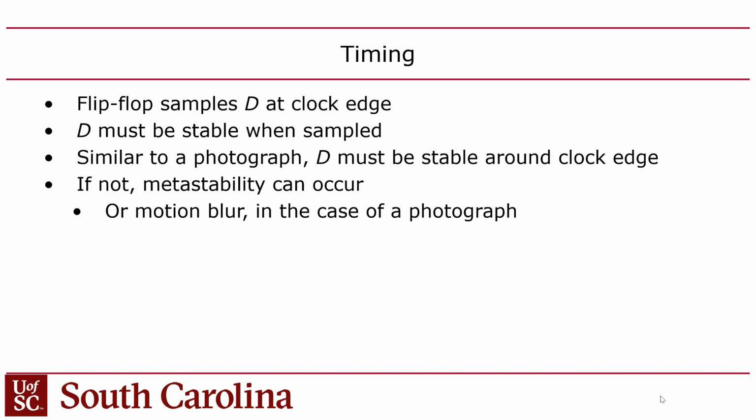If you add the setup time and the hold time, basically that creates an aperture around the clock edge. So you've got the clock edge, and then this time before and this time after the clock edge. And again, the clock edge is measured from the halfway point. So when the clock is transitioning from, say, low to high, and it's a 5 volt signal, when it hits that 2.5 volt halfway, there's a time before that, the setup, and a time after that, the hold. That time span is called the aperture time.